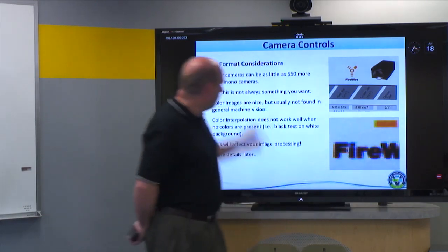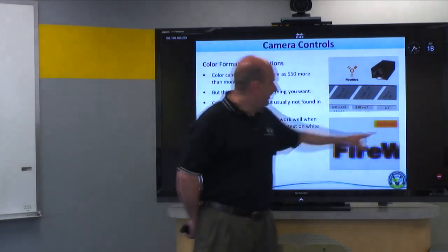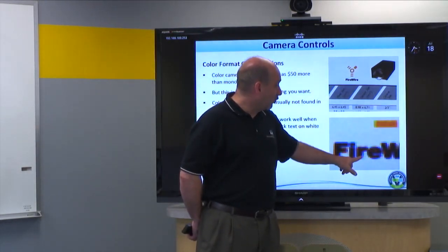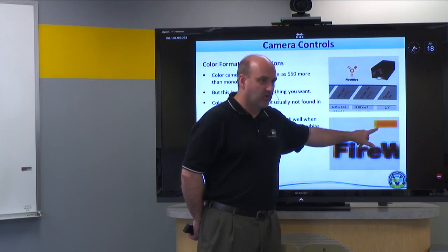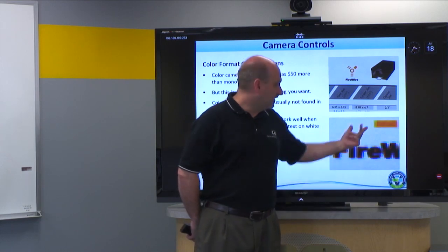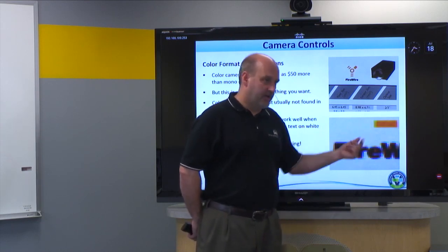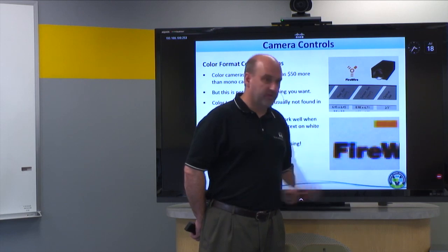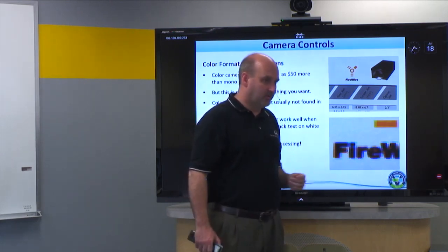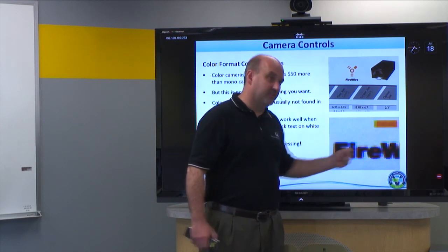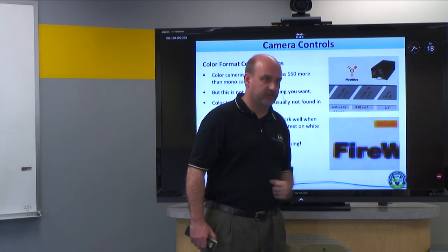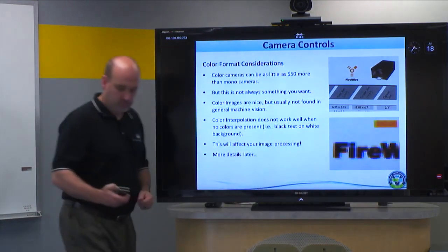In fact, one of the points in this slide is to show you that it's a function of color. The amount of aliasing you get, and how bad it is, is actually worse on black and white than it is on, say, yellow and white. So this is back to monochrome being 2D color and color being 3D color. The amount of error you get from Bayer interpolation is a function of the difference of two 3D vectors. So, depending on the contrast and color of what I'm imaging, I'll be more or less affected by the Bayer interpolation.